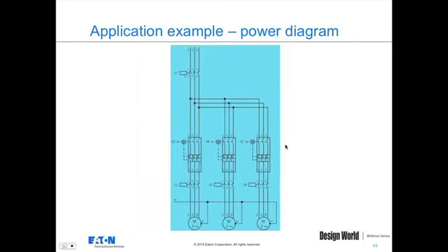The power diagram for this, again, so here's the upstream contactor, and then here are the three. This device here would be the motor controller, providing short circuit and overload protection, and then the contactor providing control. The reason there's an upstream contactor is because we want a protection level E, so we designed a category 4, which means we have to have redundancy, right? So if this contactor welds shut, we need another way to open up so that this motor turns off, and that's this upstream contactor up here. So that will provide redundancy for each of these three motors.